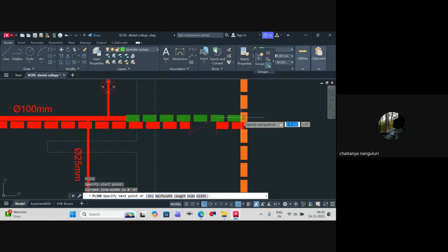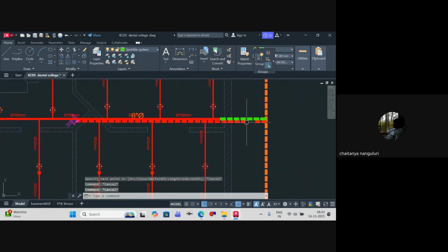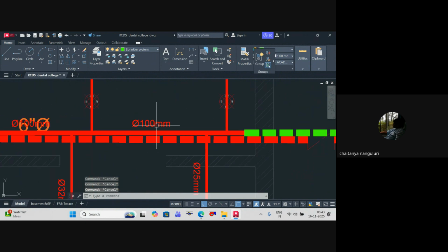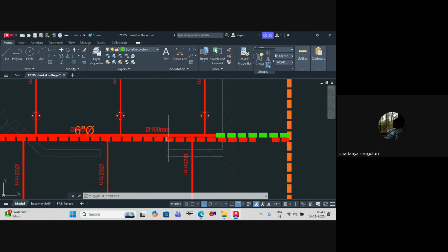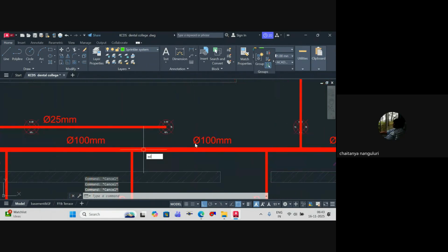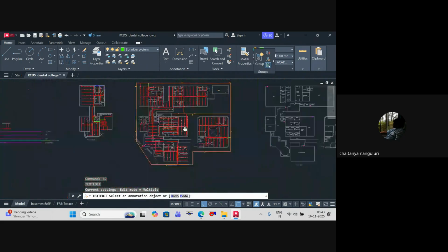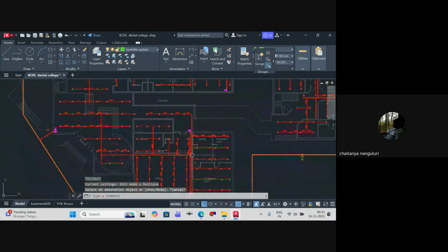Pipe sizes I've already shown you in the PPT. It's there clearly as per the hazard. You remember? So ignore these pipe sizes. I'll adjust the pipe sizes and share the final drawing anyway. Is it fine? Yeah, so probably this will be 150 dia, but let's see. Let's figure it out. I got it, the number of sprinklers connected. Similarly, whatever branches are there, we have to do all of those.